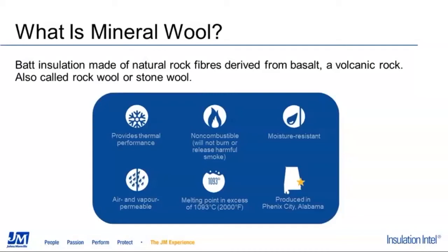You can see on the slide here some of the advantages. I typically boil this down to mineral wool really equals fire performance. Mineral wool typically costs about 50% more than fiberglass does when it is installed. So why would somebody spend that premium? It's really about fire performance.